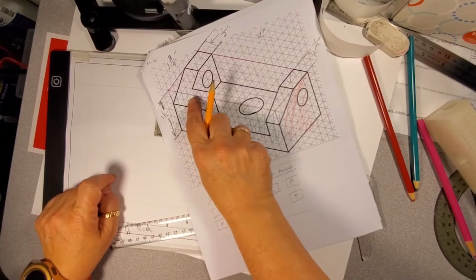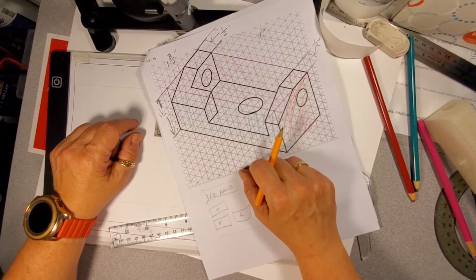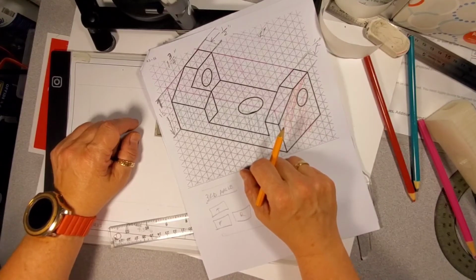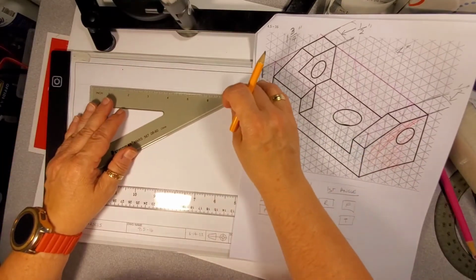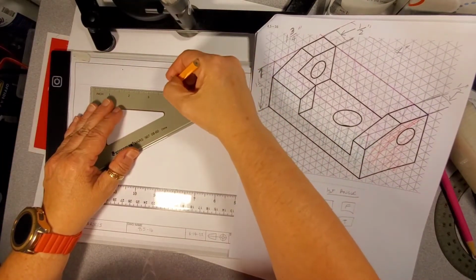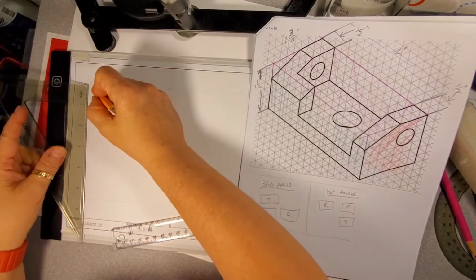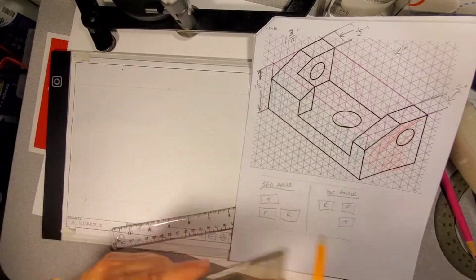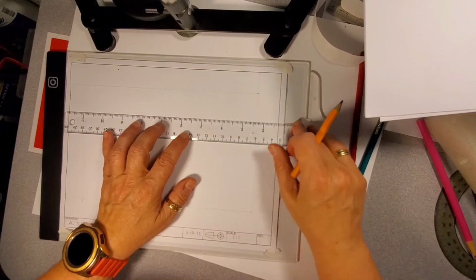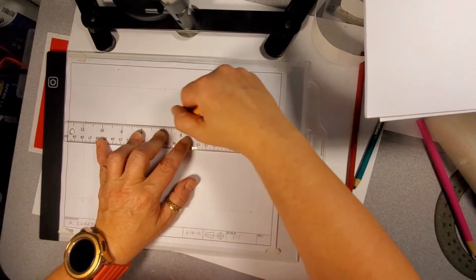So for my third angle, I've got to do my front view here. That's the front of the part. Should we do the top view first? What do you want? You tell me. Yeah, top view. Top view first? All right. Here it goes. So it's 4 inches long. So I put a little ticky. 1 3/4. 1 3/4 this way. So I put a little ticky. Then I actually draw my shape, which is just a rectangle, another rectangle.